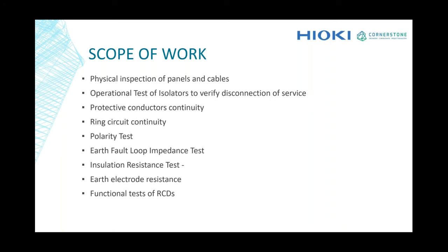And next is the ring circuit continuity test. This is to verify the continuity of phase, neutral, and earth cables between the DB and final circuits. Then the polarity test. It is the verification of polarity between phase and neutral on the circuit side.